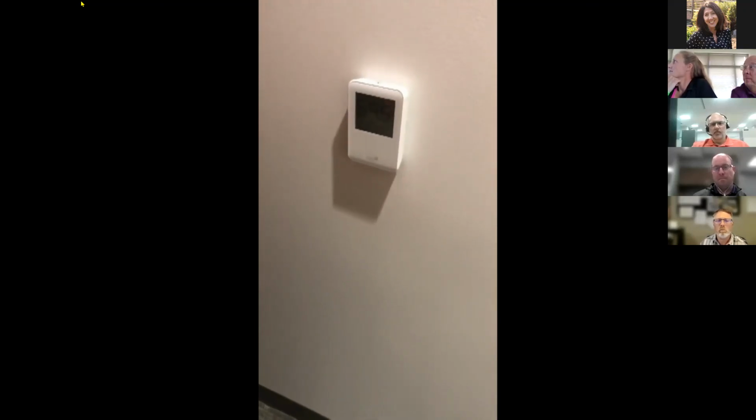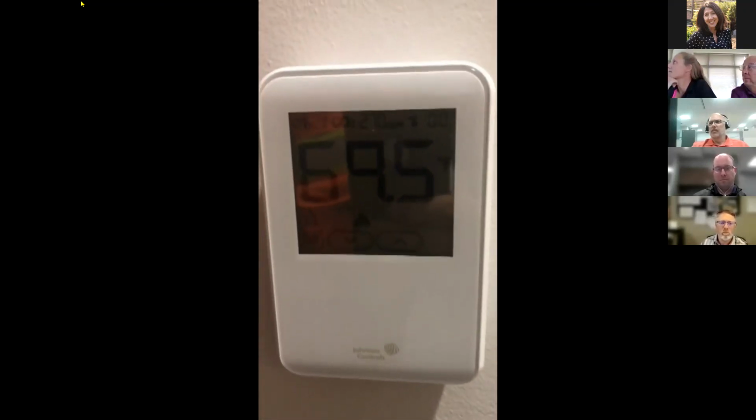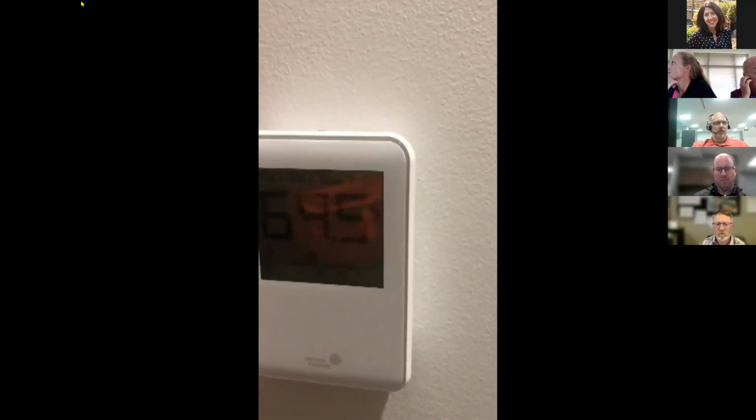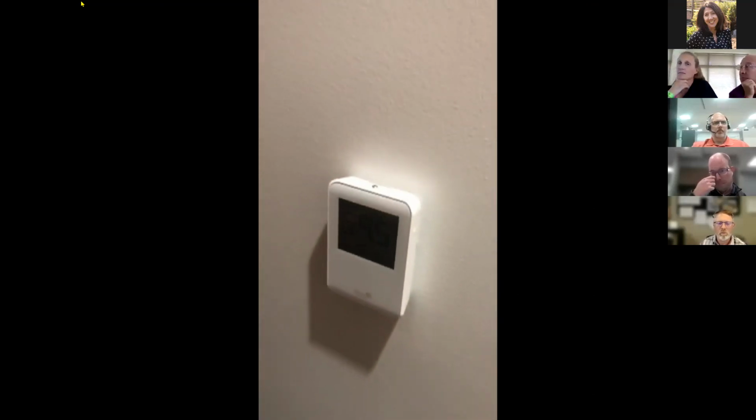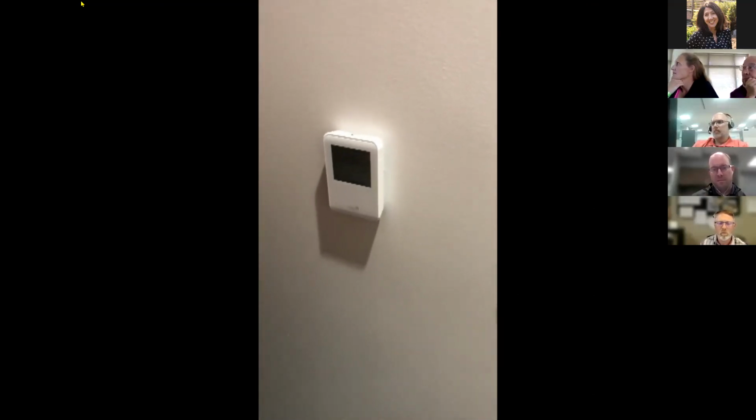Today we're testing a CO2 sensor. Current CO2 is at 270 parts per million. Our limit is 700 parts per million. One way to test the CO2 sensor is to use the CO2 test gas, or if you don't have the test gas, the easiest way is just to blow into the sensor.